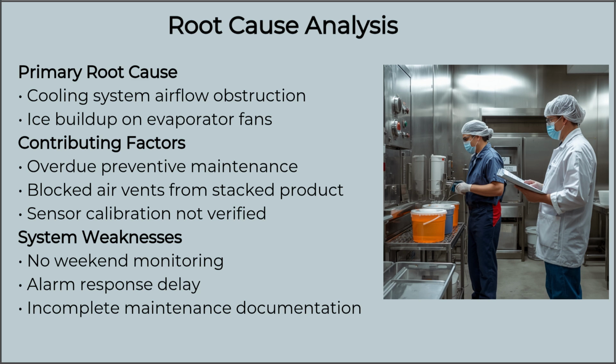Contributing factors. Preventative maintenance was overdue, and the condenser had not been serviced according to schedule. Product was stacked too close to air vents, blocking circulation and worsening the temperature rise. The temperature sensor calibration had not been verified after recent repairs, reducing accuracy.